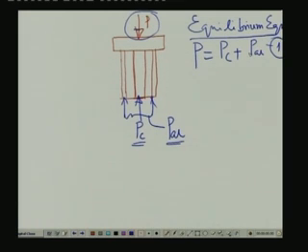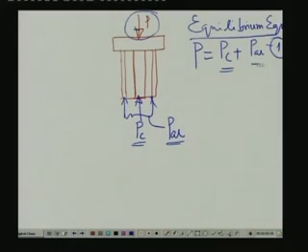Now, in this particular system, we cannot have any other equilibrium equation. So, we have only one equation of equilibrium, and there are two unknown forces, P suffix C and P suffix Al. So, two unknown forces and one single equation, hence we cannot solve this system unless we have an additional equation, and this additional equation can be generated from the compatibility criteria in terms of the deformation, and then we can solve for these two unknown forces.